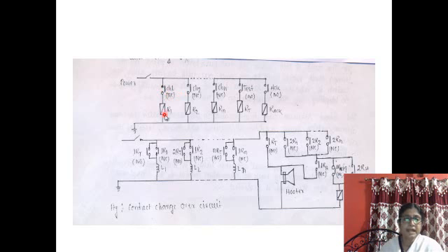So relay R1 will move to de-energized state. Now as this is in de-energized state, this contact 1R1 will be closed. Now the circuit of this path will make, and lamp L1 will glow. Are you getting my point?